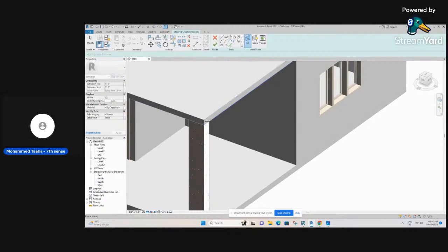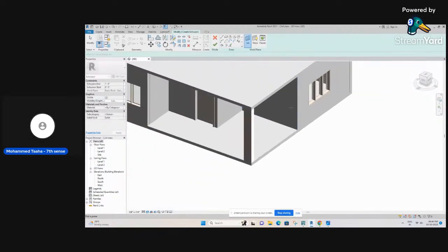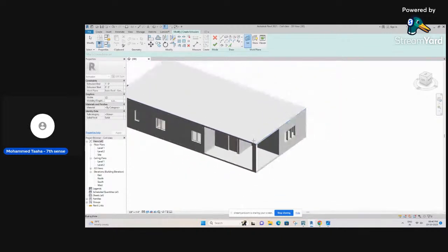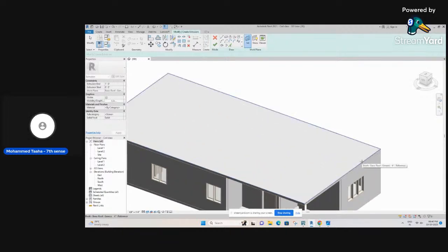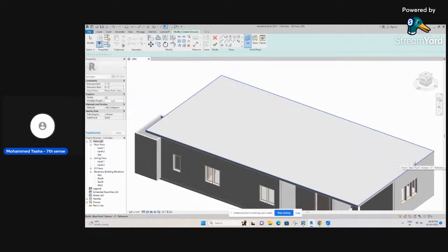You can select any plane. A plane represents the place on which you can draw any shape you want. That place is a plane. It can be any particular face of any item or any element. So, for example, if I want some component to be drawn on the top of the roof, I'm going to take my cursor to the roof, go near any of the edges of the roof, and you can see four blue lines which represent the plane.